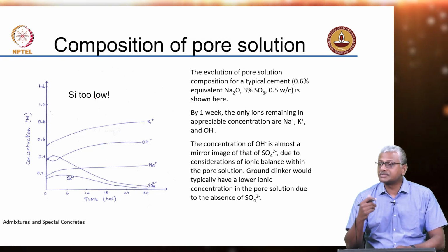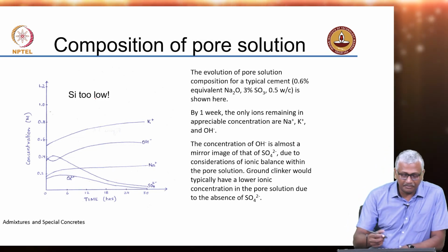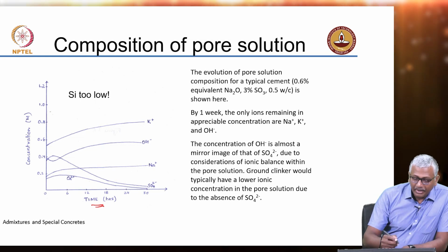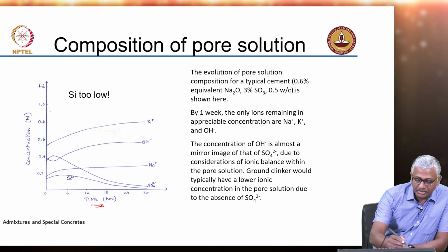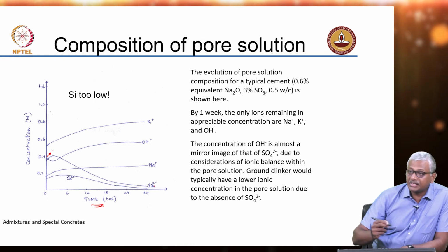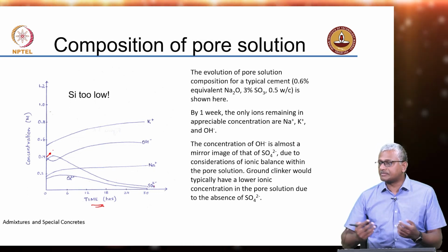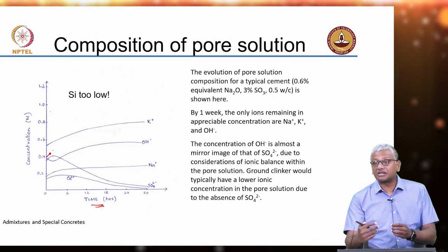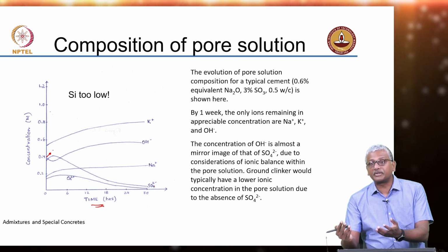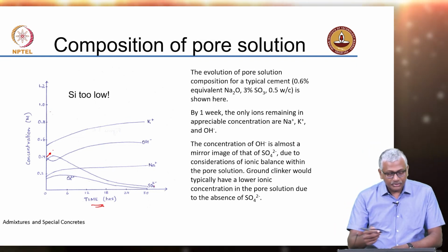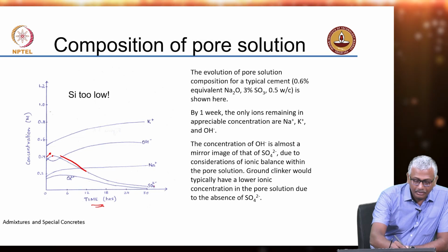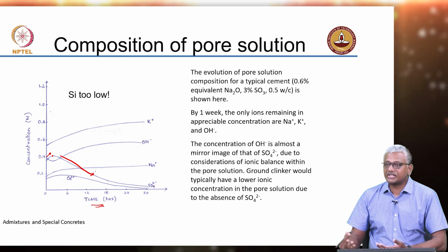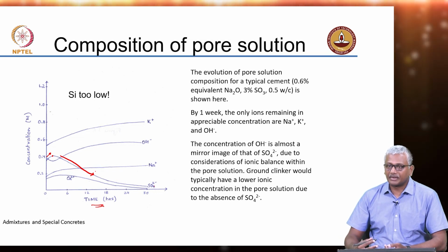If you take normal cement paste after a certain period of time, you will see that, so this is plotted in terms of concentration in terms of time, and you see here that the sulphate concentration started off increasing initially because there is a sulphate species in the system that gets dissolved slowly, right. Gypsum is available, other sulphates may be there, some sulphates may be released from the alkali sulphates that are already there in the clinker. So, you have a quick buildup of sulphate, but then sulphate concentration is going down because of the combination of sulphate in the reactions with the aluminate, right.